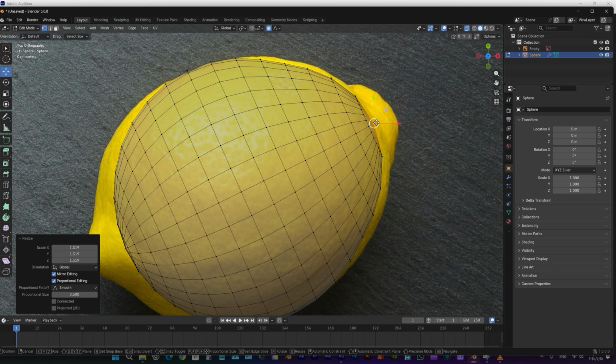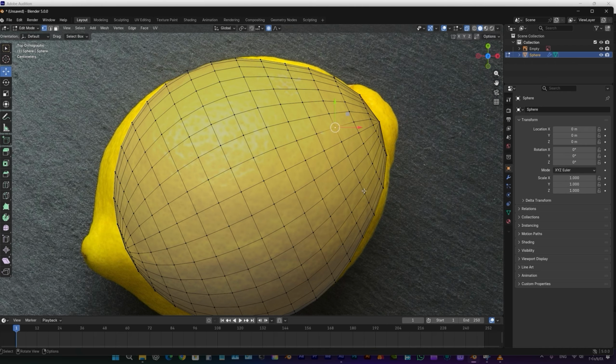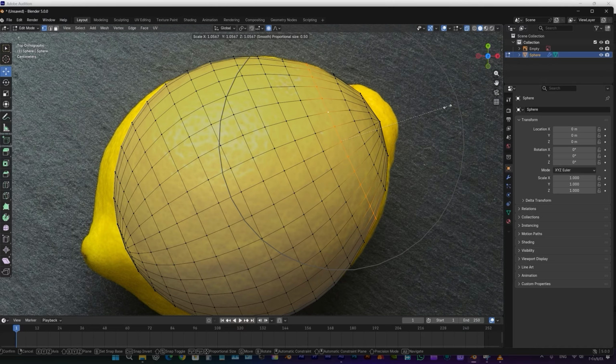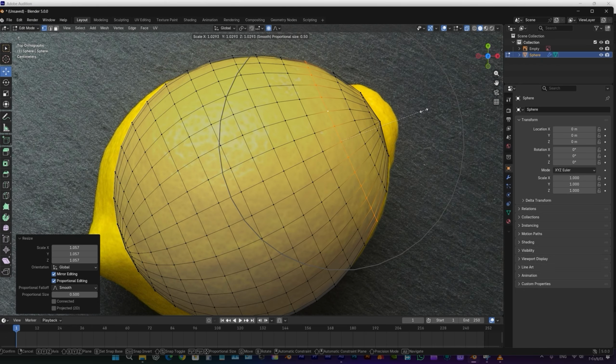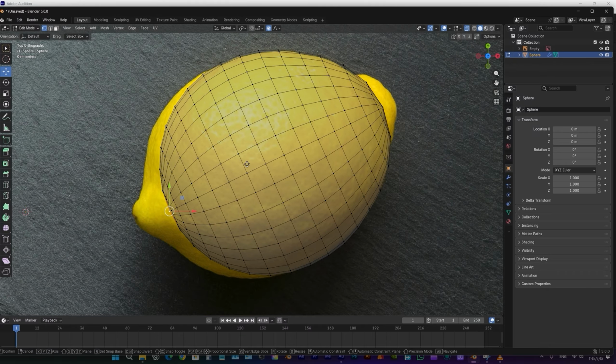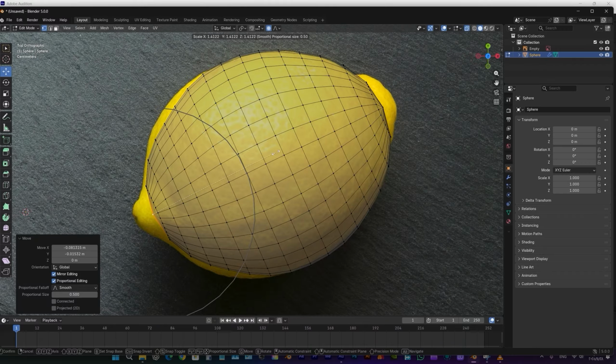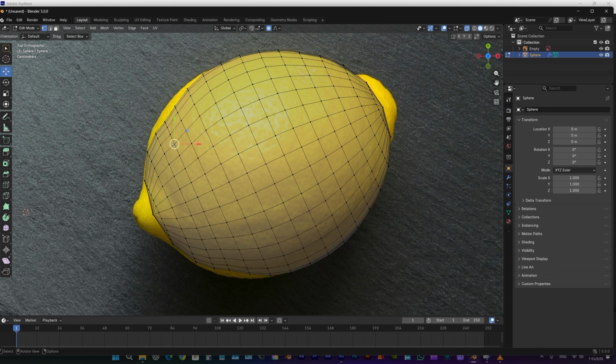It's looking good now. To select this whole line, select the first point, hold Alt, and select the next point. Now, let's scale up this part, press S, and make it a bit bigger like this. Drag it over here. This part too, let's scale it up slightly to tweak it. On this side as well, select this, press J, and move it a bit. Here, choose Scale and make these points bigger.